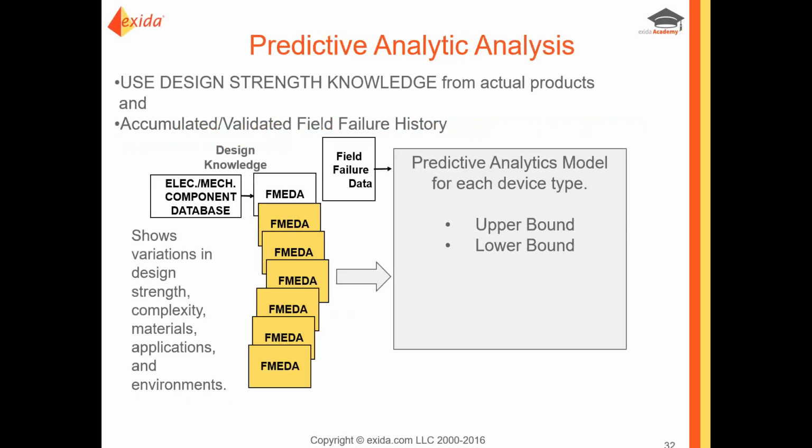For now, I will simply tell you that Exida has done a lot of work with a lot of different manufacturers. And for every product category, we have developed a good understanding of the variations in design strength, complexity, materials, applications, and environments. The FMEDA technique predicts a failure rate as a function of application type and operational environment.